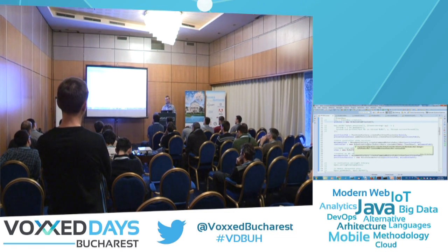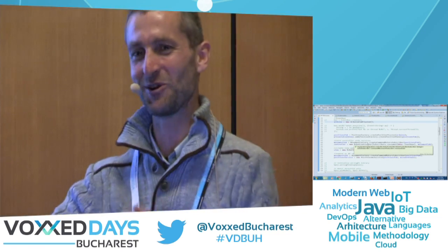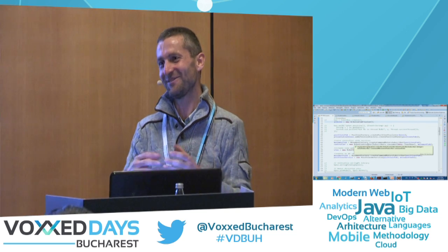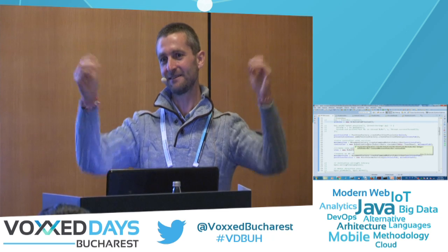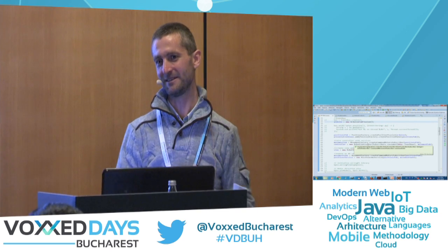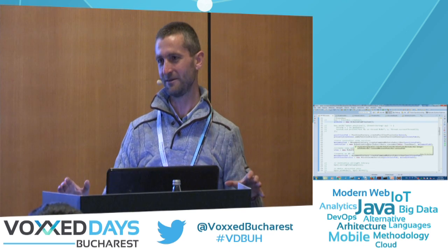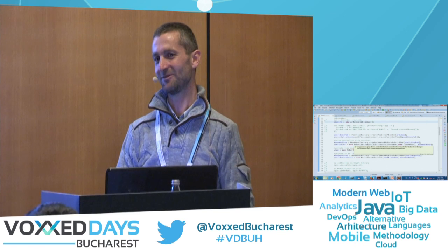Actually, we have a very clear separation in this domain because motors can be commanded, encoders can be listened to. We don't have a way to mix them, even if we want to. But at a higher-level facade, we can expose both of them to the clients using the same interface. At low level, they're implemented separately, using different types of, for example, processors or concurrency implementations if we want.